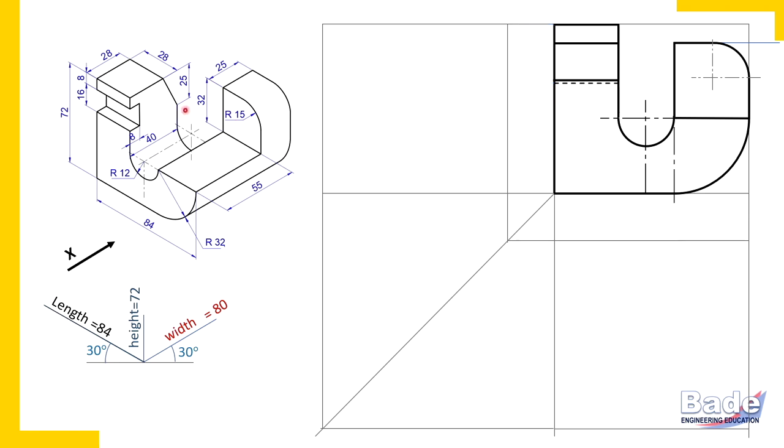Check. Now, one more thing. From this corner, there is a vertical edge. Check here. A corner is formed by three edges. So from this corner also there is a vertical edge. That is hidden. Now from this corner there is a vertical edge up to the surface.